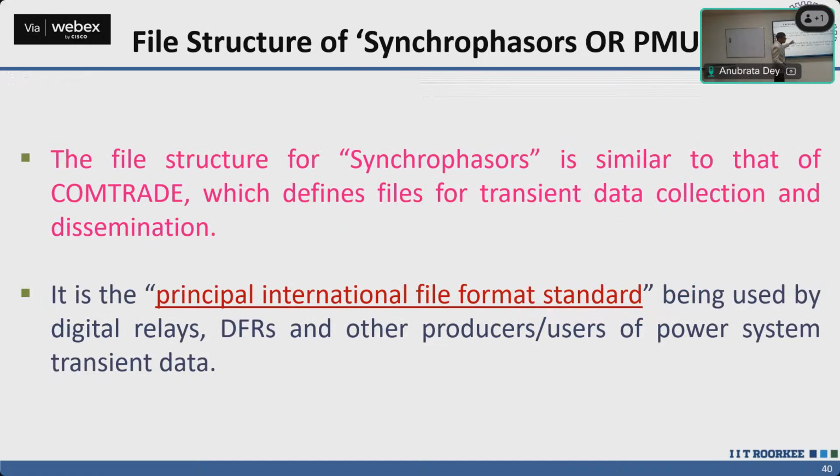Now, what is the file structure of this PMU? How is the PMU going to send the data? In what form? This is very important, right? The file structure of all synchrophasor devices, PMU or PDC, is based on the COMTRADE file, right? This is the file for transient data collection and dissemination, which is very commonly used. It is used by even fault recorders also.